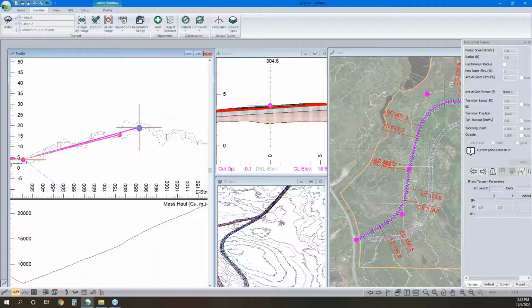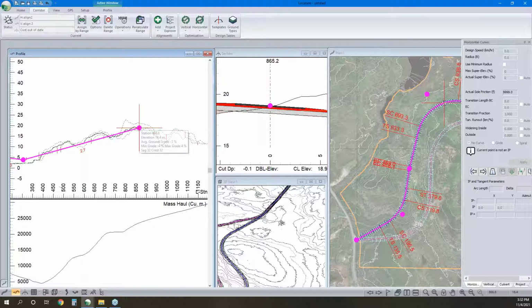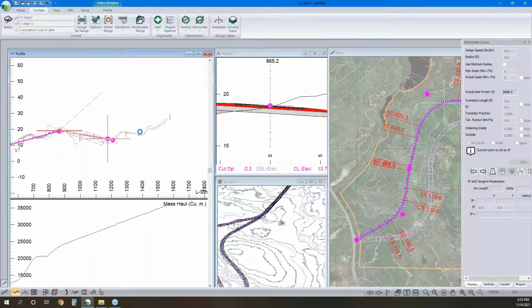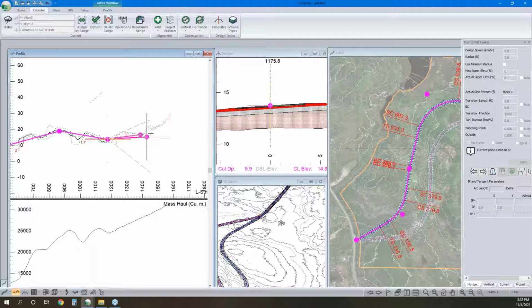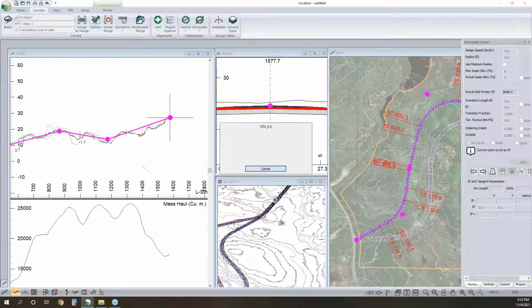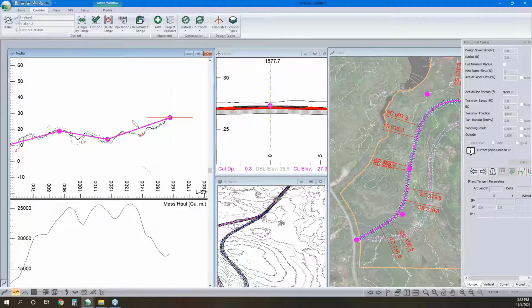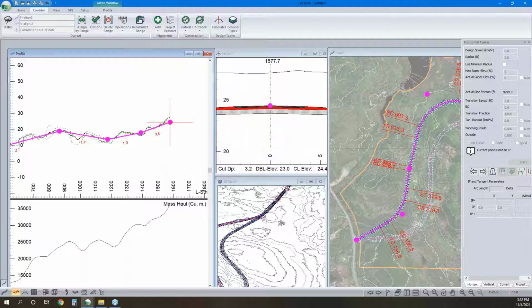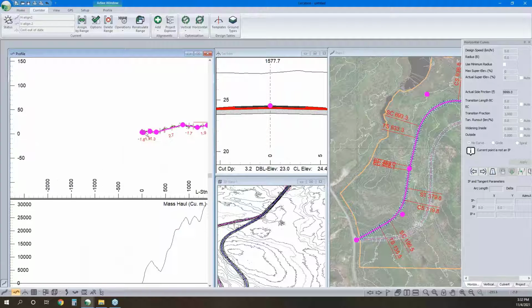And again, at this point I'm going to use the optimizer, so I don't have to worry too much about my material movement or getting the road in the right place. I'm just doing a quick click through, and I'll worry about the details after. I won't even add curves here, but we absolutely could add curves if we wanted them. So I've got a little bit of a hump there. We'll drop that down. So now I know that it's relatively close to what I want.